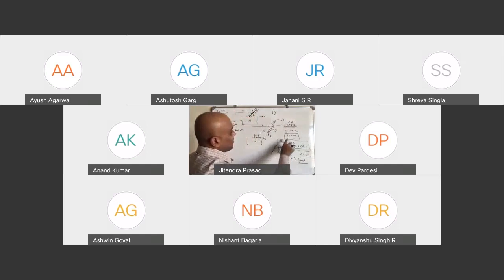Okay. Now, what is the total torque acting? Total moment about G has to be equal to Jg times theta double dot. So that's the equation. This is Newton's second law of motion. Total moment in this case, if you see, clockwise is positive for us. Theta is going this way, so clockwise is positive.